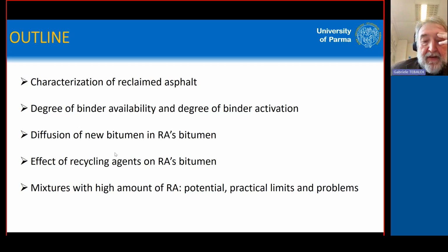We will see some effects of recycling agents on reclaimed asphalt bitumen, and we will spend some time looking at some specific problems that we can face. Basically, I faced it in my research activity, but I think it's something that everyone can face when the amount of RAP goes up above 30%. So we can define a high amount of reclaimed asphalt. We will discuss some practical limits and also some problems related to this particular choice.